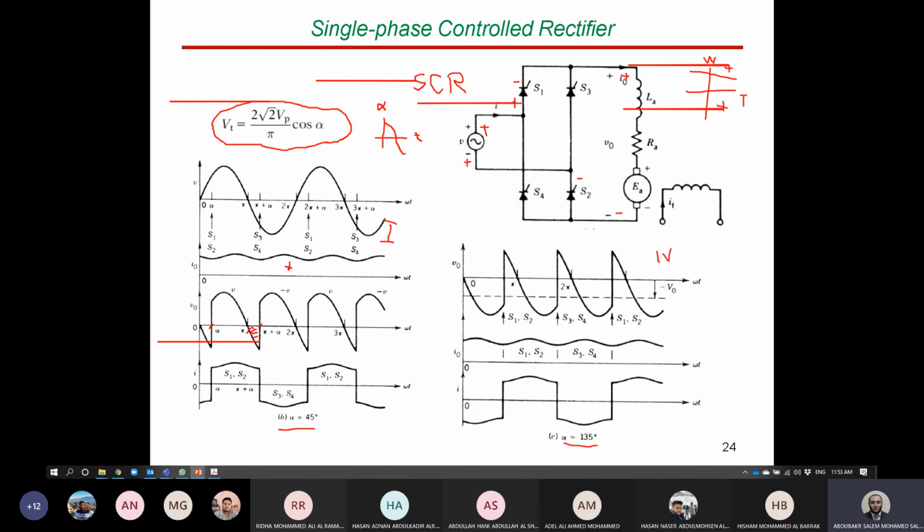All the time here, guys, this negative voltage with positive current means power is negative, which means the power will be returned to the supply again. So we have here inductance, which is storing energy and returning this energy again to the supply. So all the time, the supply will see the load as inductive because there is an interaction, storing and returning the power again to the supply.